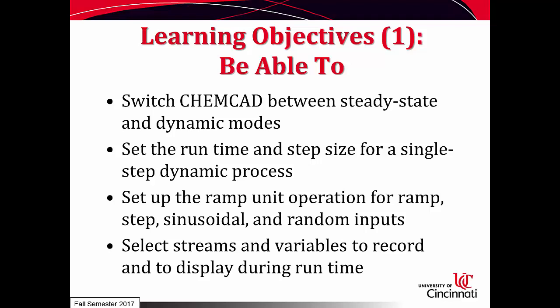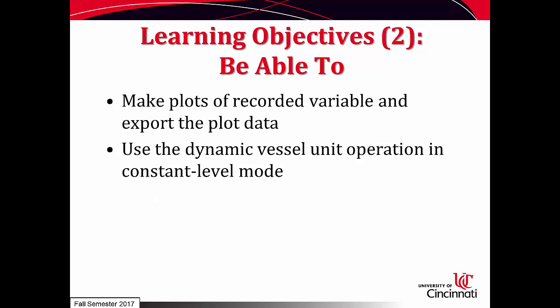You should be able to select streams and variables to record and to display during runtime. You should be able to make plots of recorded variables and export the plot data to Excel. And you should be able to use the dynamic vessel unit operation in its constant level mode.